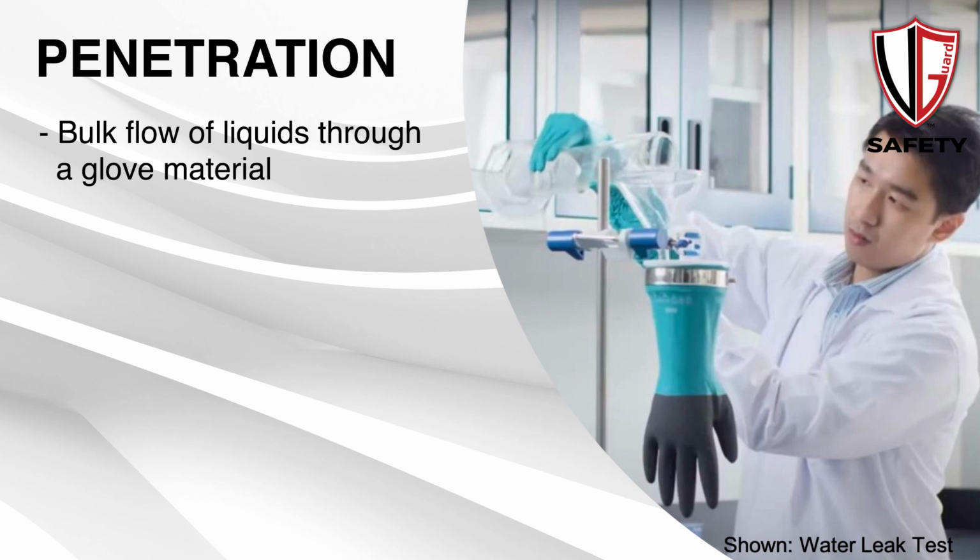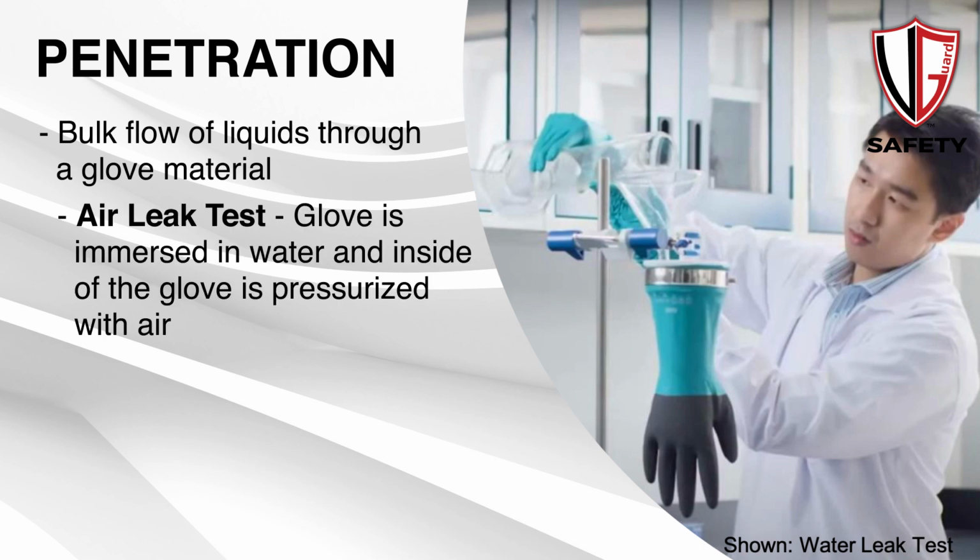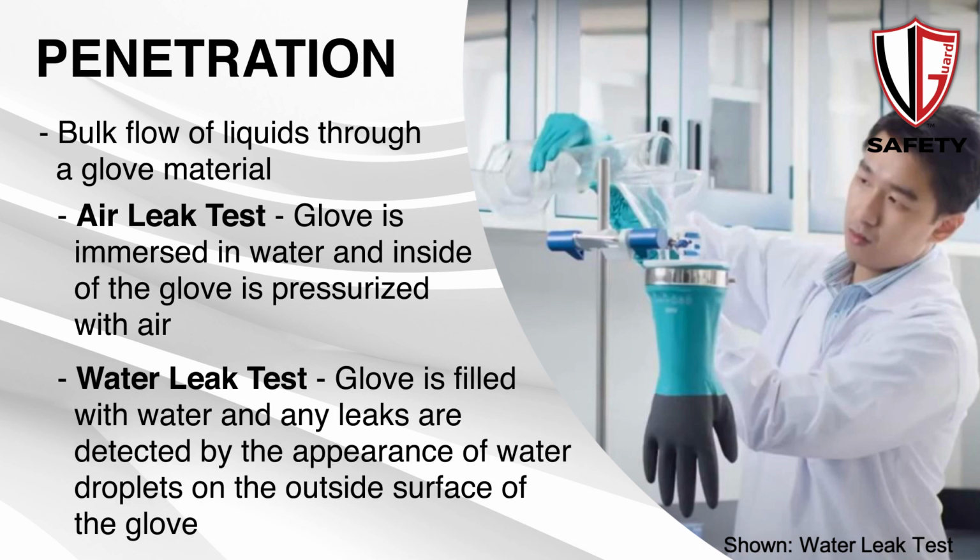A penetration test is performed in two different ways. An air leak test, which is where the glove is immersed in water and the inside of the glove is pressurized with air, and also a water leak test, which is similar. The glove is filled with water and any leaks are detected by the appearance of water droplets on the outside surface of the glove.